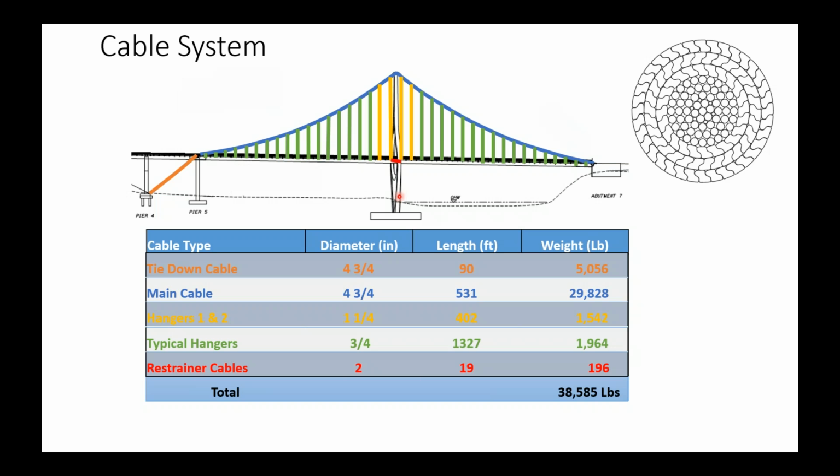we talked about. So in general, the main guiding document for cables in cable supported bridges is the PTI guide spec. Unfortunately, that document is primarily written for highway or railroad bridges, and it really doesn't have a lot of details specific to pedestrian bridges. And mainly the difference here is the type of cables used.